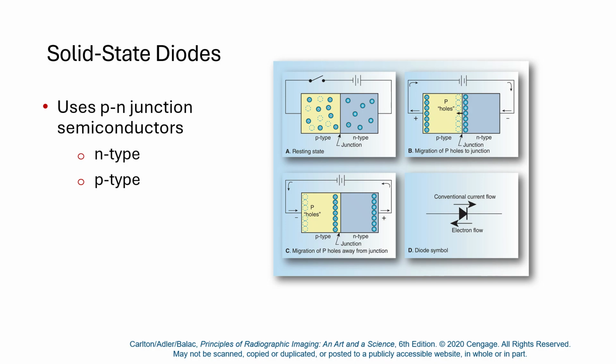Yes, gallium. If we add some atoms of gallium to silicon, well, that's going to have one less electron in the valence. And so it's going to create an additional vacancy. And that's p-type doping. Okay? And so there are more holes available for electrons to jump into in p-type. Okay?